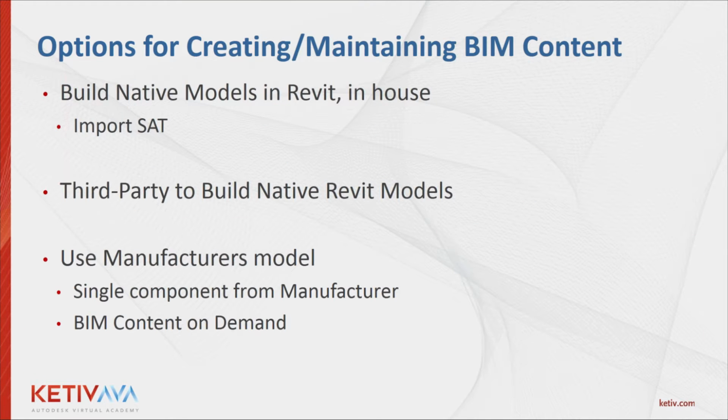So if you're an architect, the thing you'll want to know is, first of all, I have something that's not necessarily in Revit. Maybe it's an HVAC system, a sink, or something like that. That's a specific one. So you have to ask yourself, do I want to create this myself, or do I want to import it? You can import SAT files, also known as ACIS files, into Revit. So you can do this in-house, basically.